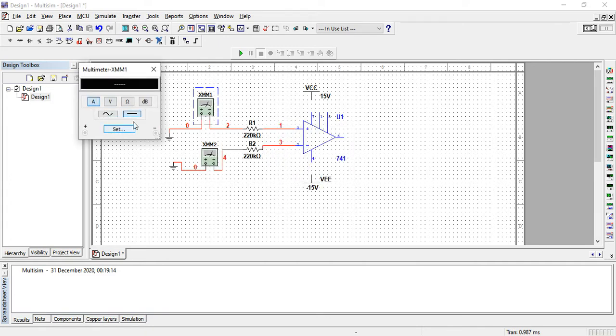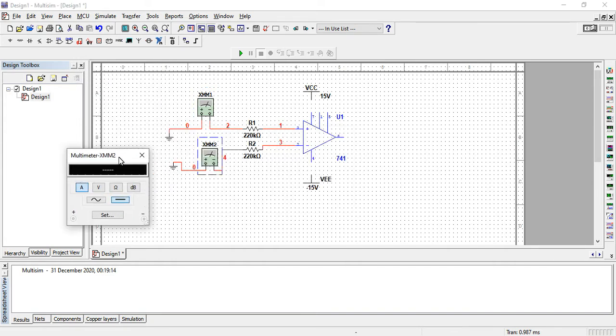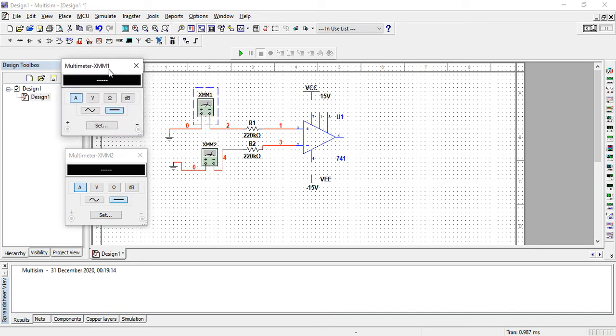Go for the ammeter and it should be DC, and I'm keeping both of them open. What else? You have to connect the supply, with your positive to your 7 terminal and negative to your 4 terminal, and this is your output. And let's just initially run it and see. Okay, there's a set of readings of your IB1 and IB2.